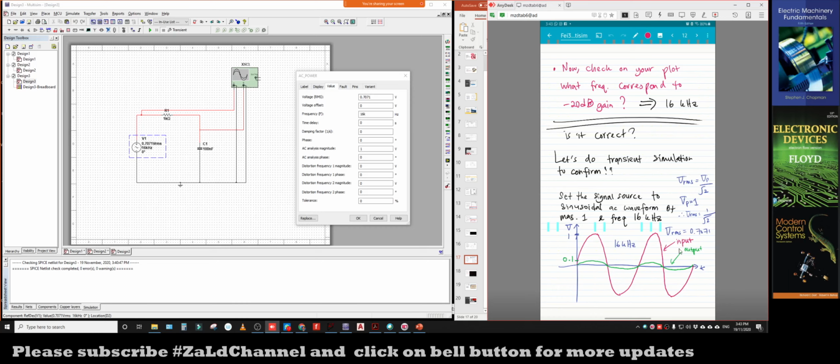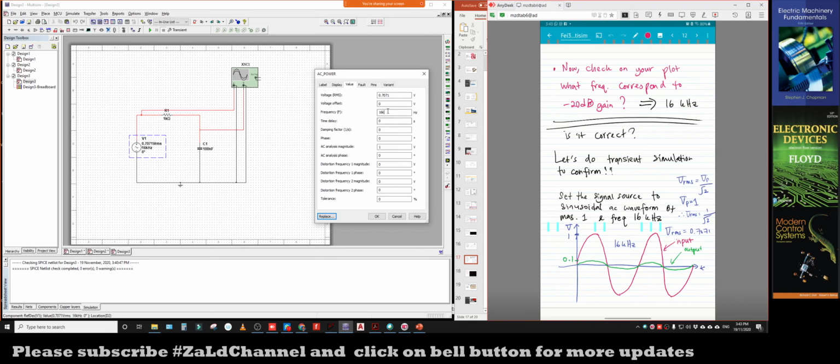All right, so as you can see for my sketch here, the red one is input, the green one is the output. Okay, so we are going to simulate this to confirm that 16 kilohertz corresponds to the signal of negative 20 decibel. So we specify this 16 kilohertz for source frequency, and AC analysis magnitude we set to 1, and voltage in RMS.